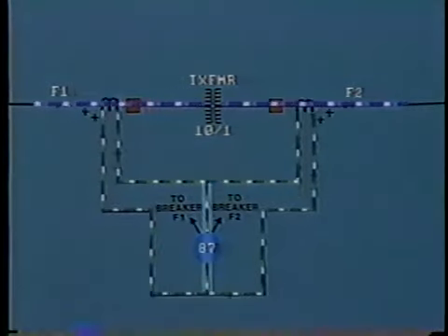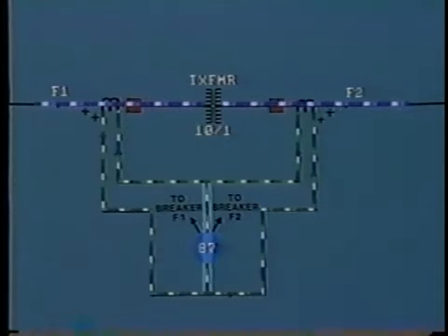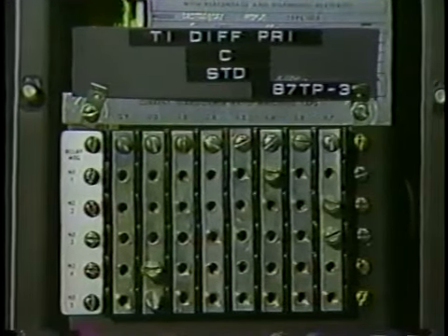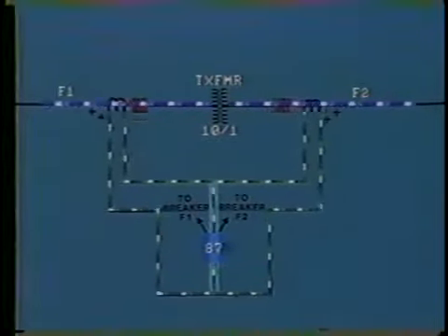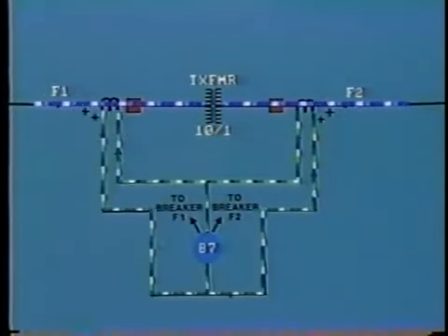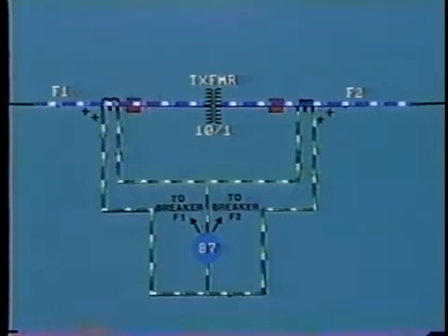This means that a small current, let's call this the error current, will flow through the differential relay operating coil. In an attempt to reduce this error current as far as possible, differential relays are typically provided with a number of taps to help balance the CTs. But even with this, a small error current usually does exist. Now, under normal operating conditions, this will probably be below the pickup value of the relay, and so will not